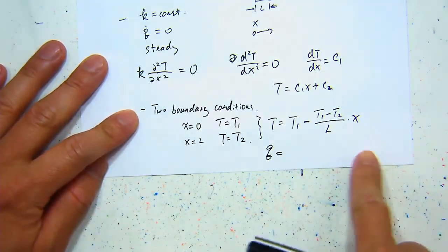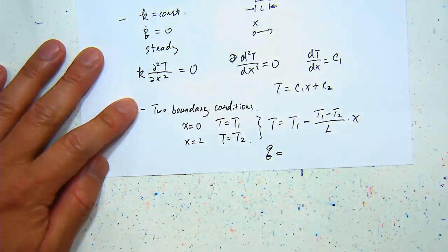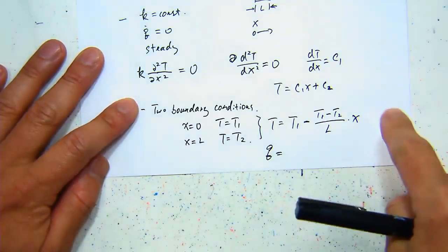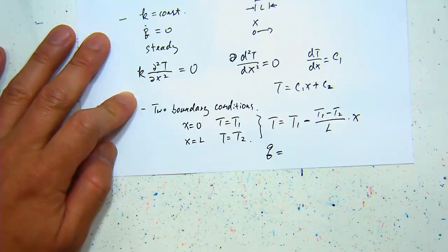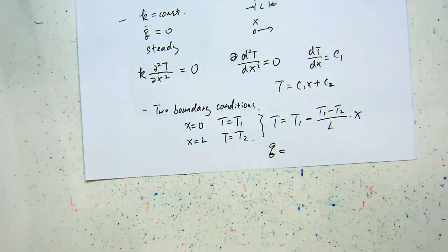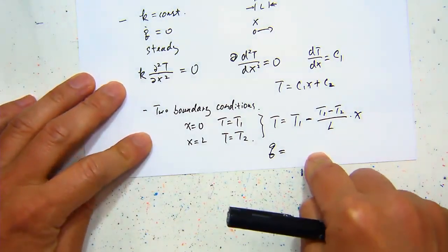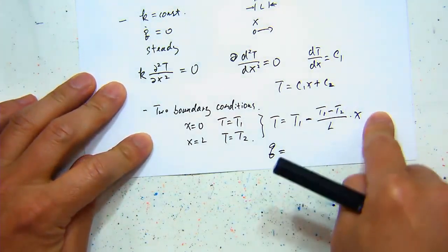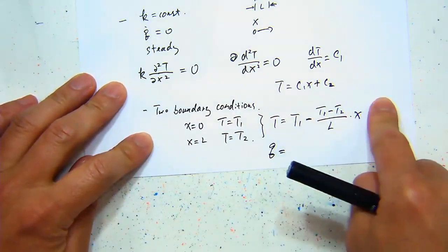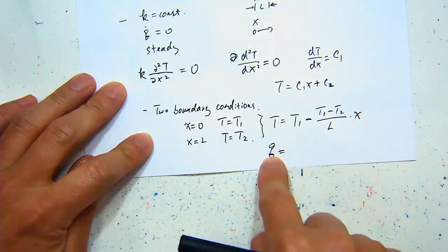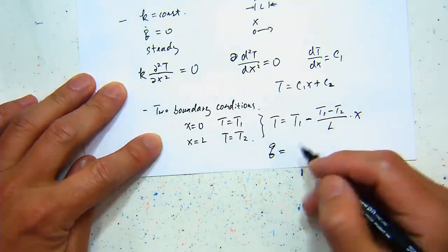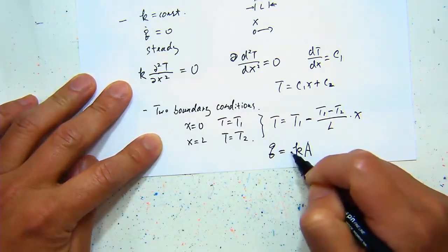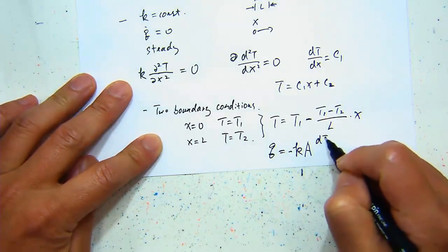The heat transfer rate, how do we obtain the heat transfer rate? If you know the temperature distribution, how do you get the heat transfer rate? Rate equation. Yep, Fourier's law, essentially. You know how temperature is distributed in a medium, and the rate equation for conduction, that's Fourier's law, which contains the temperature distribution term. So if you recall, that one is minus kA dT/dx.